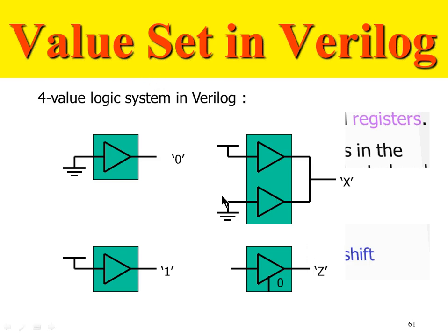Assignments can be done in Verilog in this fashion. Now this is a continuous assign statement. Assign out is equal to not in. So the right hand side in will be inverted. This evaluation will happen, and then the out signal will be updated with this inverted value of input.